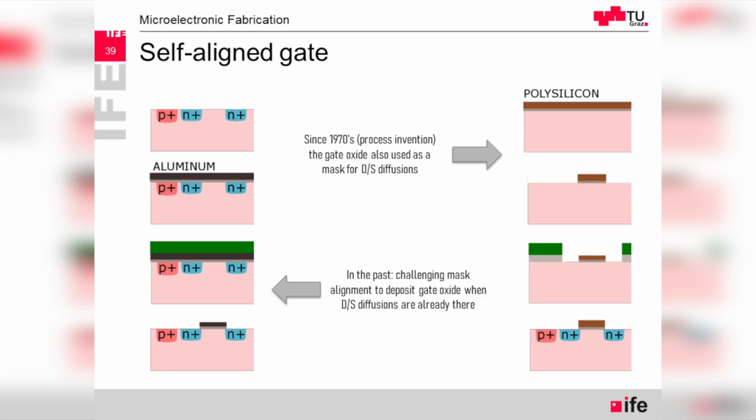So like that, we know that these two N+ implants on both sides of the gate, we don't have to then try and target with the gate on top of those two implants to exactly match the channel length. And we also don't have problem of uncontrolled diffusion. We can much better control where the implants are located.